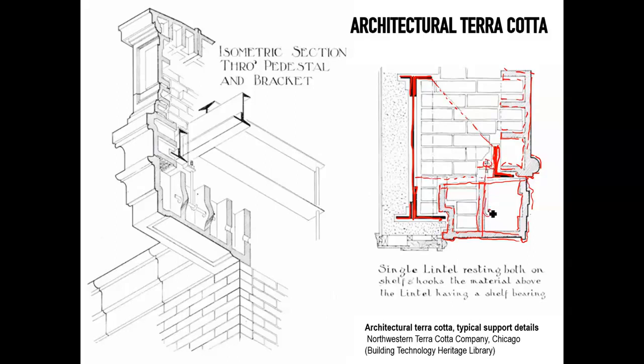It's coming down and it's supporting a rod that is also supporting this terracotta underside or expanded lintel over the window. You can see this very nice 3D that sort of explains what we just said. You can recognize here a C channel and an angle bracket supporting another system of support with another channel, and you can see clearly these J bolts that are supporting this through rod of steel that is sort of running inside these terracotta profiles.